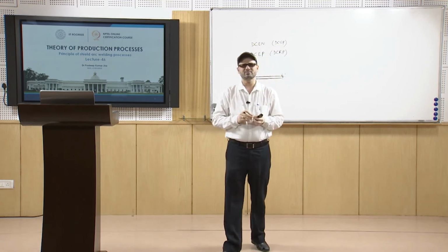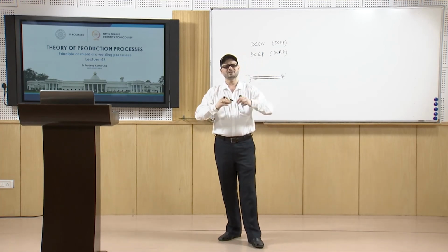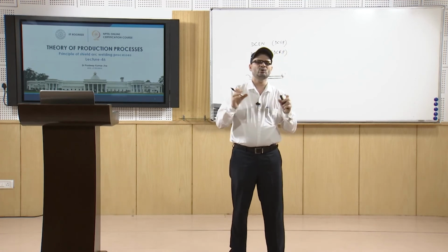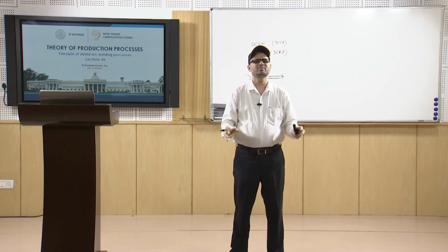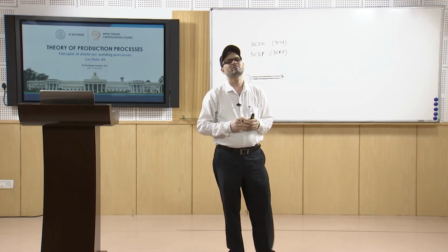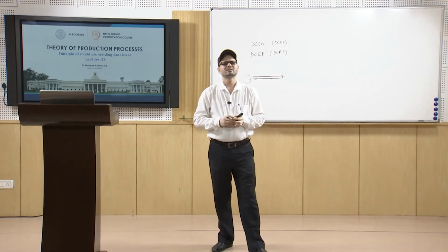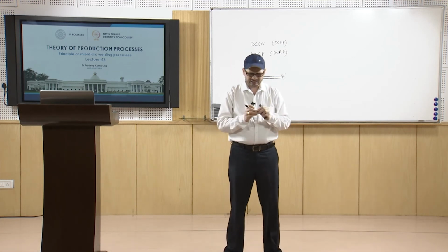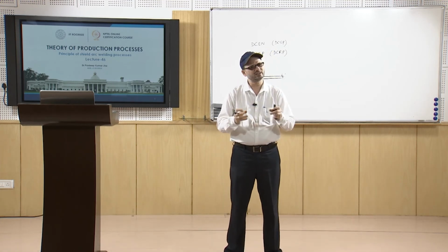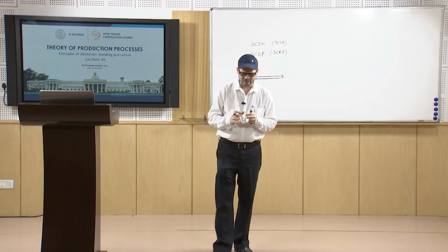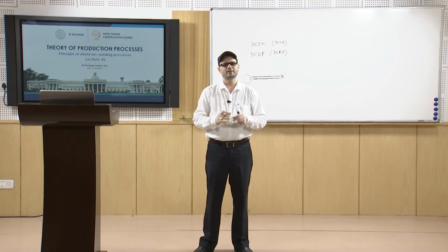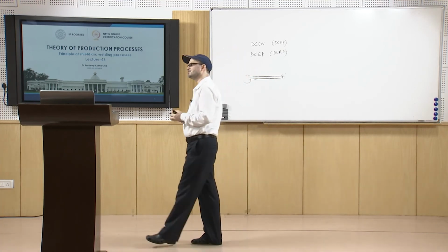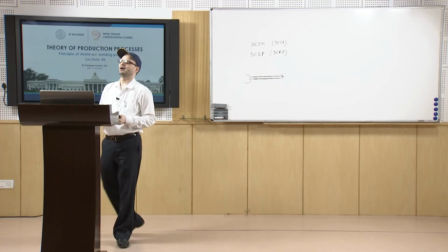In submerged arc welding, the welding is submerged under granular flux. The flux which is used is granular flux, so the arc is not seen. The arc is completely surrounded by the granular flux, and the flux is continuously supplied.